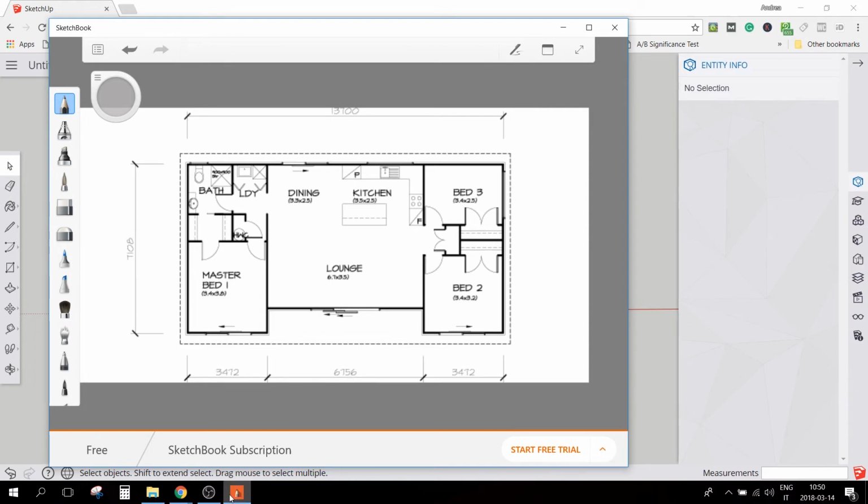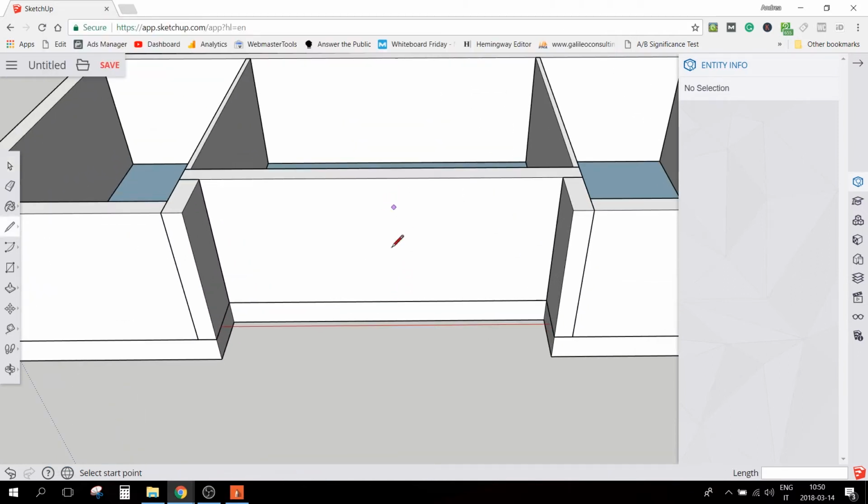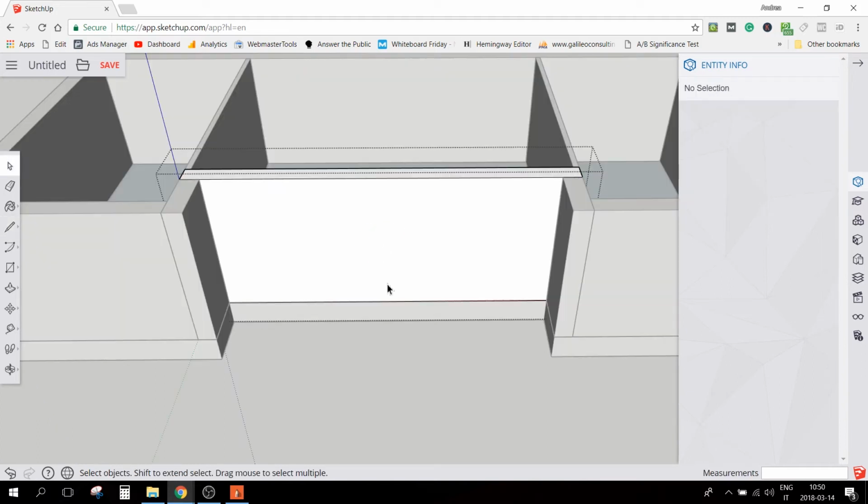Let's make 3 meters. So go back in SketchUp, I go on the face here, I go inside the object, I take the midpoint here and I go 1500, so half of the size on this side, end point of the line that I just drew, and I draw here.